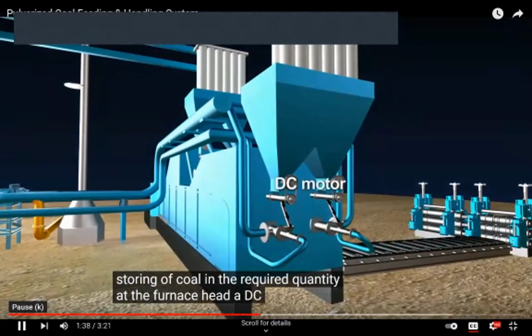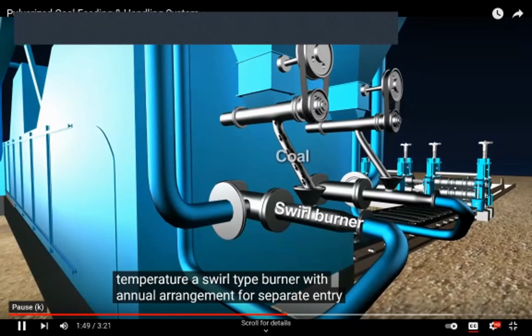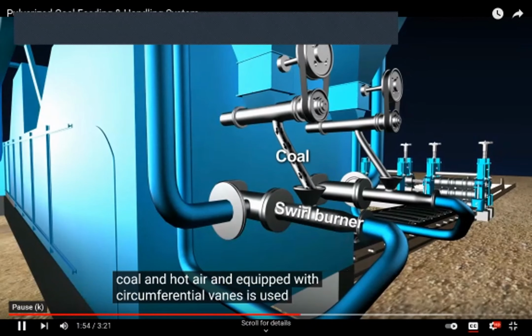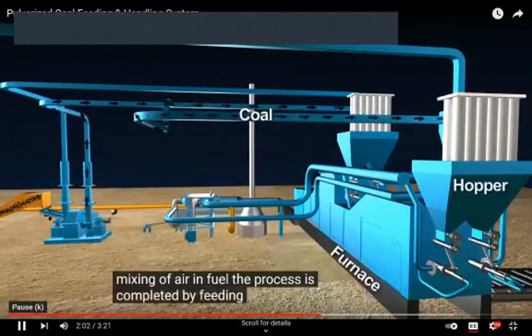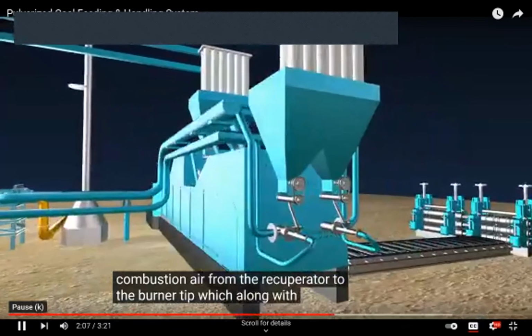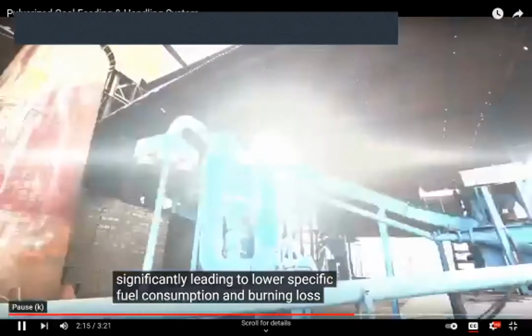at the furnace head. A DC motor-run screw feeder controls the coal flow to the burner based on the furnace temperature. A swirl-type burner with annular arrangement for separate entry of coal and hot air and equipped with circumferential vanes is used in the system to ensure proper turbulence and mixing of air and fuel. The process is completed by feeding preheated combustion air from the recuperator to the burner tip, which along with the swirling motion improves the combustion significantly, leading to lower specific fuel consumption and burning loss.